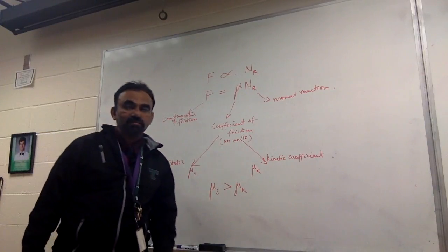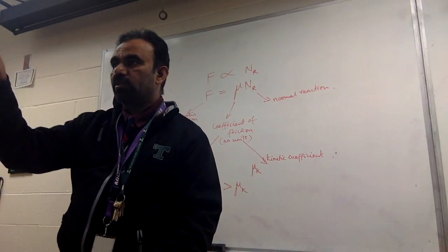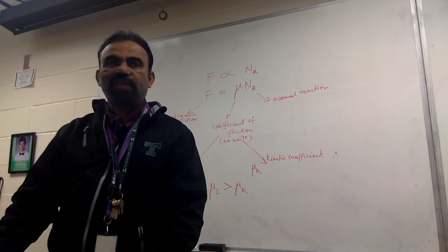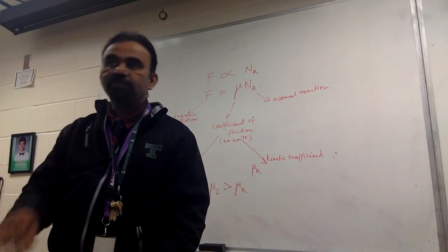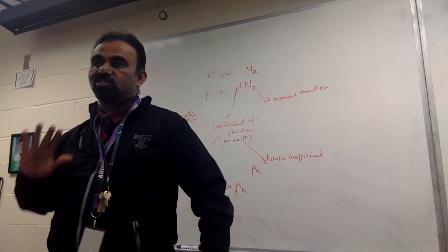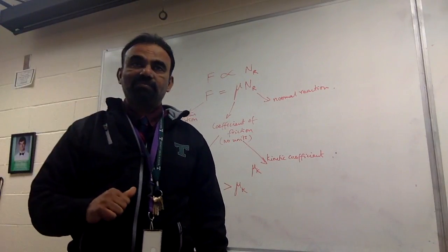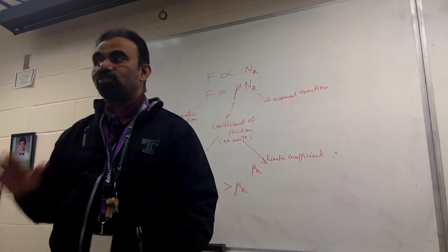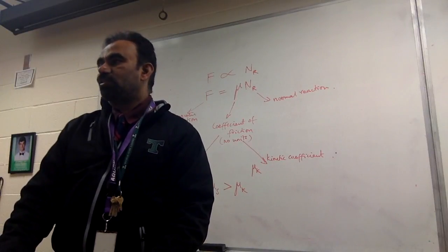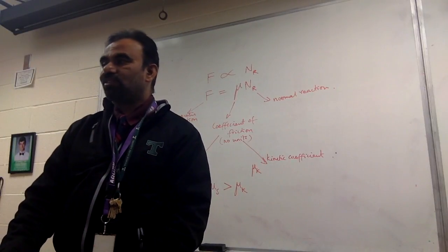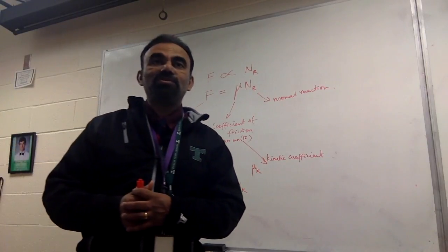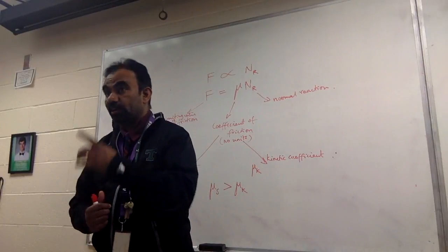Let's say for rubber tires with the road, the coefficient of friction is probably 0.8, 0.9. That is if it is at rest. The moment you slam the brakes and it starts gliding, then it's kinetic, and that drops. That's why once your car starts skidding, it's hard to get it back under control, because you're talking about kinetic friction now, not static friction. So it's always important that you don't skid or hydroplane.